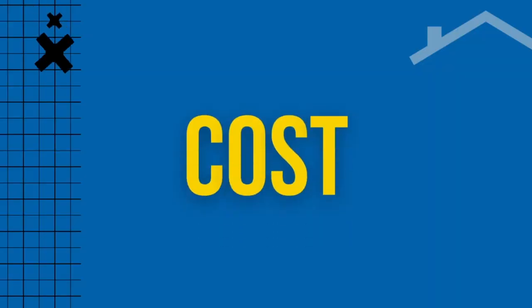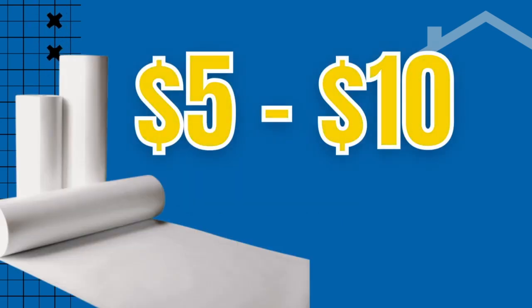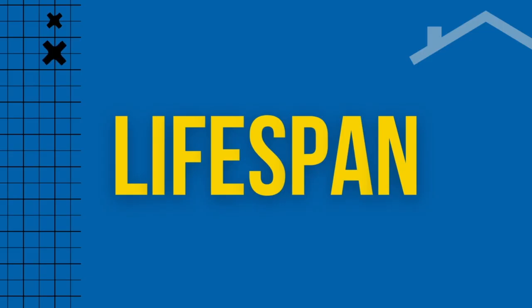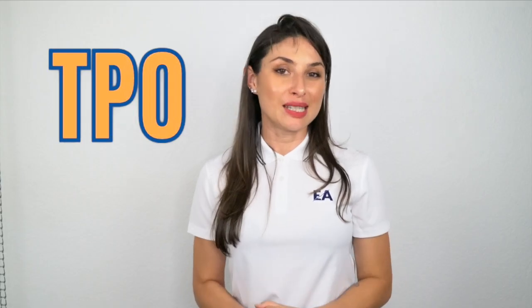Cost. Now, it would usually cost anywhere between $5 to $10 per square foot. Lifespan. If installed properly and maintained well, TPO should last anywhere between 15 to 20 years. So what is the downside to TPO? Well, TPO is a much newer product, which means it has not been tested as much as all the other materials. It also does expand and contract due to the weather, so it will be affected by this.